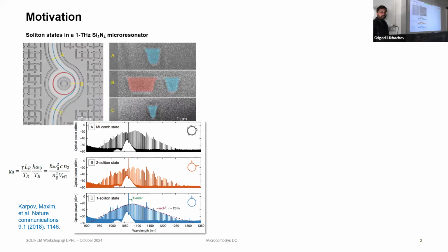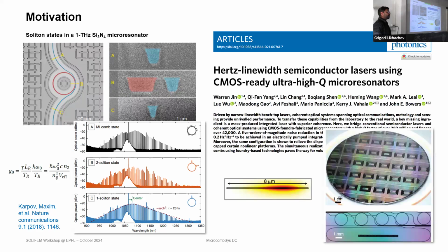Another good application to minimize bending loss is to design lasers. I purposely chose two very opposite examples. In the case of microresonator frequency combs, you would like to exploit the non-linearity of the material. So you want more of your optical mode to be inside the core, inside the Chi3 material. That's why you need thicker waveguides, and thicker waveguides can help you design tighter resonators, and you can exploit the non-linearity of the material.